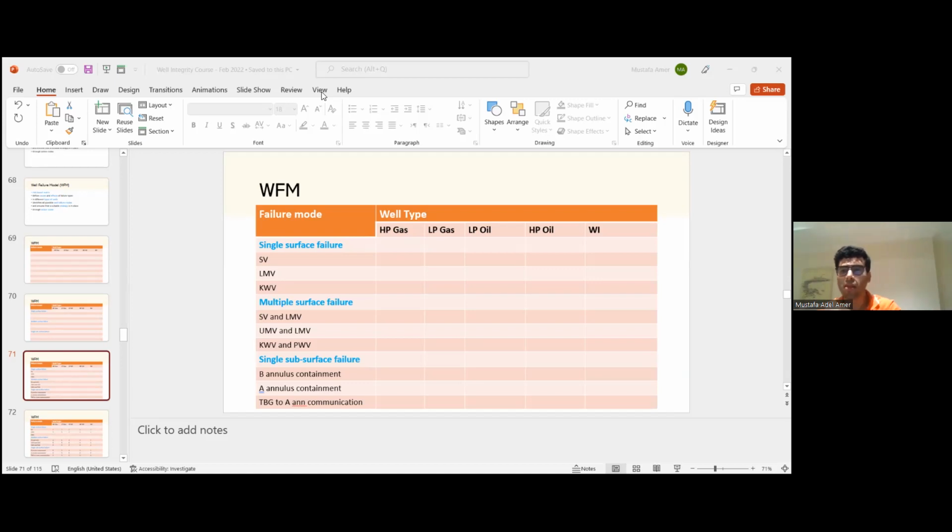You have a problem in the annulus itself, away from the tubing. So maybe fluids are sneaking behind the packer, or the packer is leaking. Maybe you have a high pressure gas well, and the gas is leaking behind the packer. If you get gas from the annulus, but if you don't get gas from the annulus, then maybe there is leakage in one of the casing shoes, or maybe the casing itself is leaking from one of the surface water formations. That's why you need to collect this fluid and see its salinity, analyze it, and see if it's hydrocarbon.